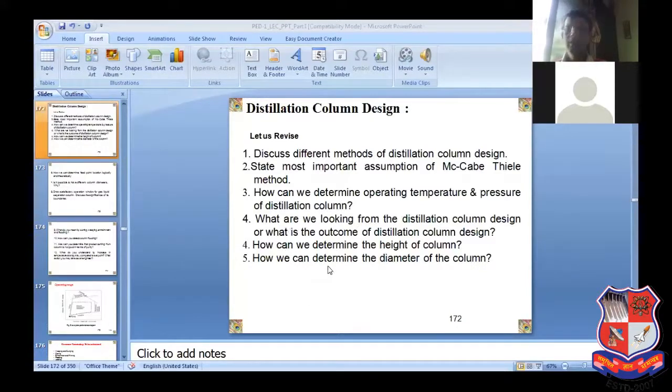Fine. So it means that if we consider the liquid flow rate in a distillation column, the column is designed in two sections. Above the feed is considered as the enriching section, and below the feed is known as the stripping section. So there are two different sections in the picture. In each section, for example, tray number 1 from the top above the feed, that is the liquid flow L1, L2, L3, like that.